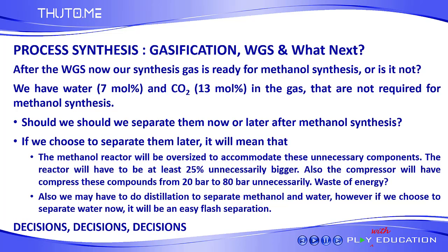Okay, after the water gas shift, now our synthesis gas is ready for methanol synthesis, or is it not? If you look at our stream, we have 7 mole percent of water, we have 13 mole percent of carbon dioxide. These two components are not required for the methanol synthesis. So we need to start thinking about what we are going to do. Should we separate this? Should we remove water and carbon dioxide before methanol synthesis?